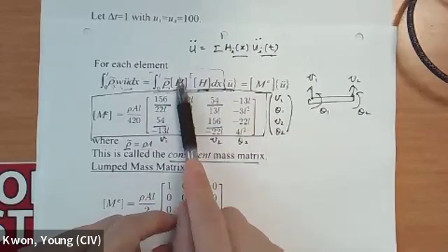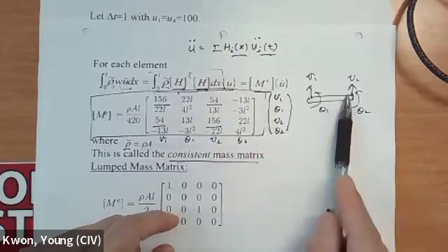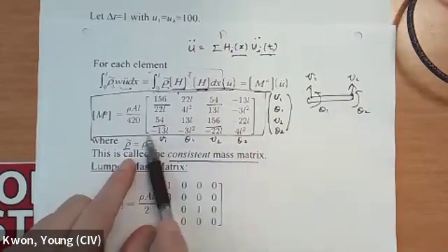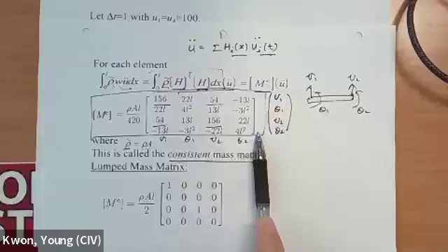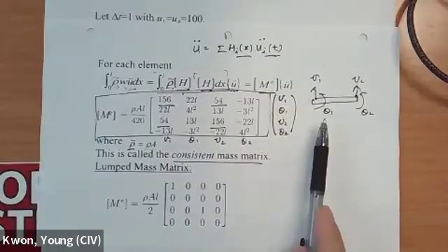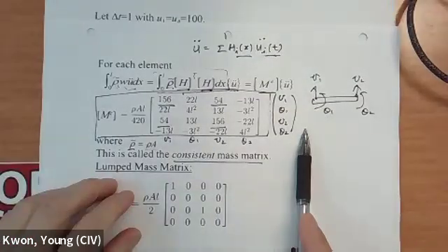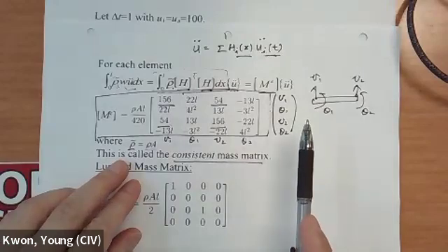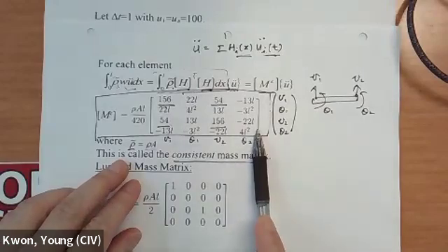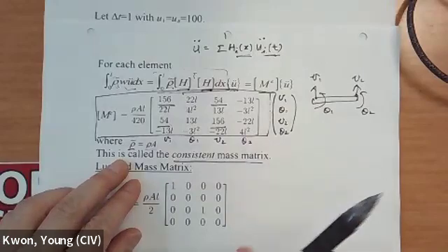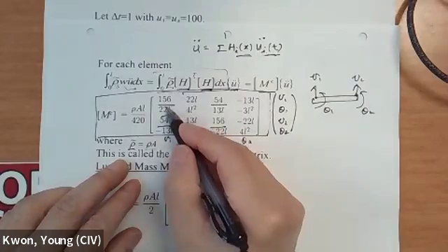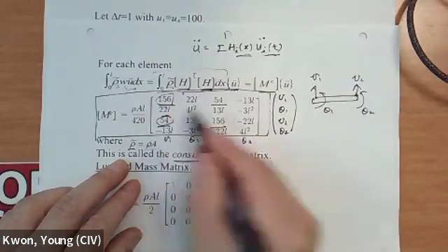And then if you plug in the shape function we developed in chapter 8, we have this matrix. This is 4 by 4 because each element has 4 degrees of freedom. And I told you that this mass matrix is conserved in terms of linear mass. Linear mass involves only those 4 terms.